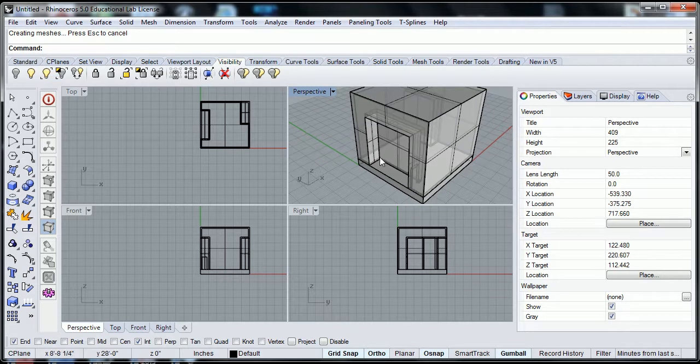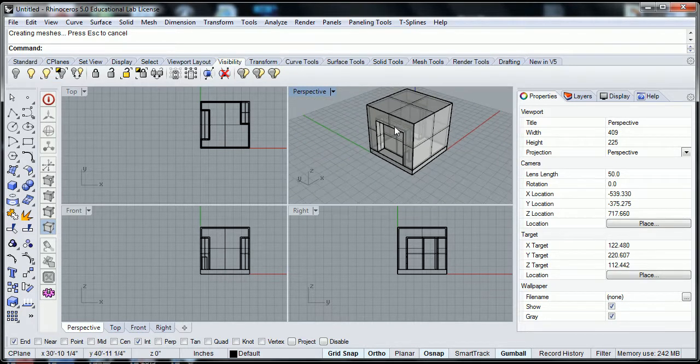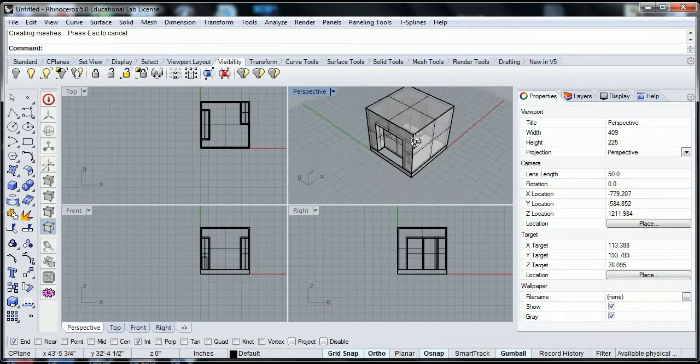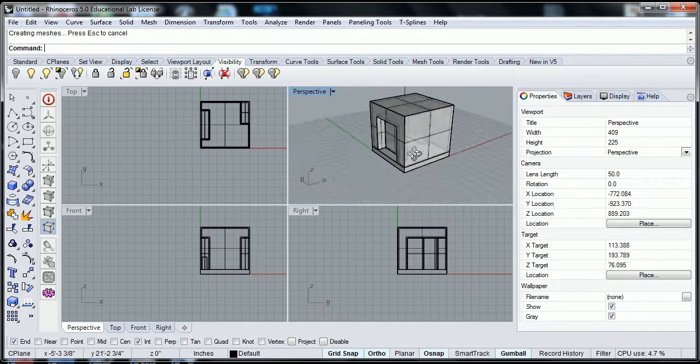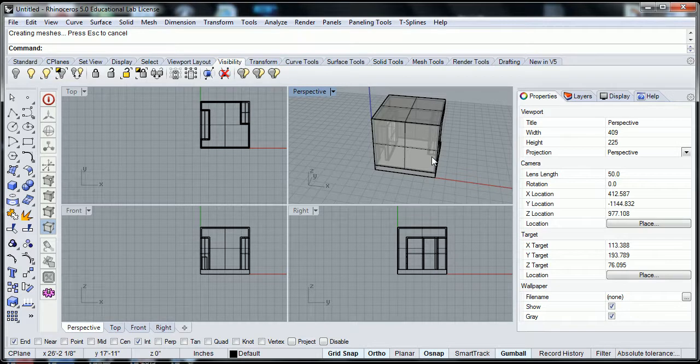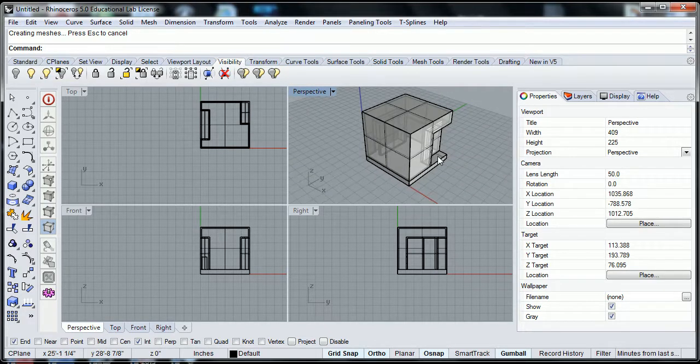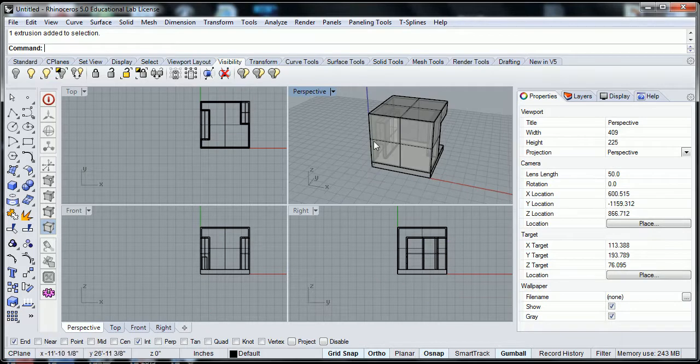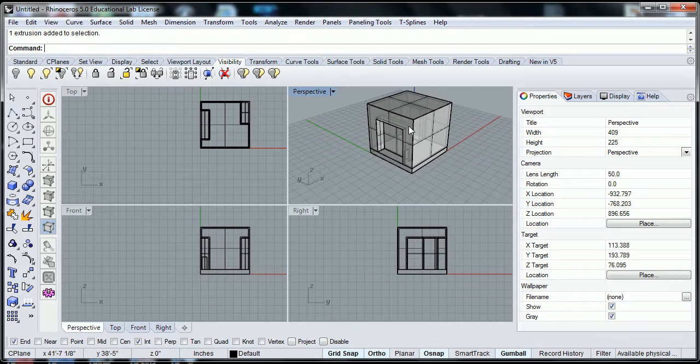And in that way, you will make several openings for your windows and such, which in the design class you'll get instruction on how to do. But this is one of the quick ways to create your 30 by 30 by 30 box with the floor level at 3 foot and all the walls ready to be punched. From that point on, you could refer back to your first subtraction cube that you did, and make your design. All that's left is where you put your apertures, where you put your openings, so that it is a pleasant design, right?